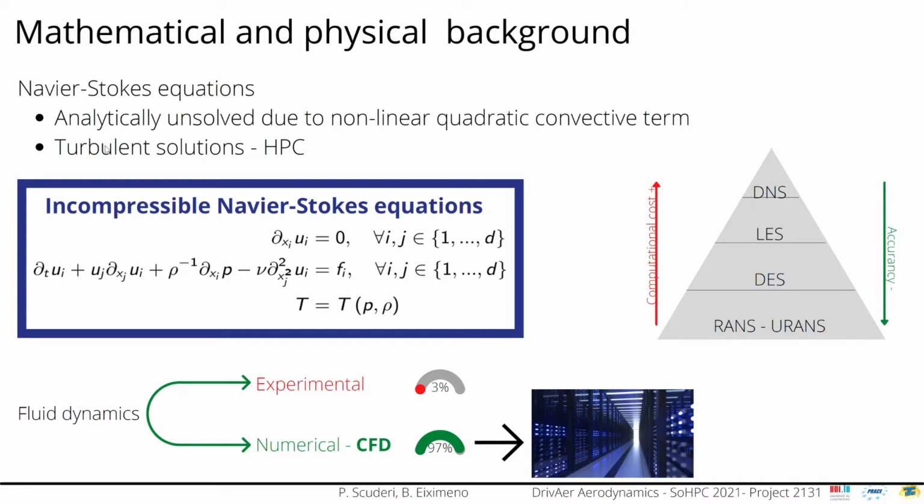In practice, when the Reynolds number is very high, the Navier-Stokes equations are highly sensitive to limited variations in the initial conditions. Hence, turbulence needs to be accurately modeled. To do this, there are alternative approaches based on the level of accuracy that we want to reach. This sketch shows the increments in the computational cost associated with a more elaborate numerical solution. In our work, we use RANS equations. However, if you are interested, in one of my blog posts I explain the different approaches.